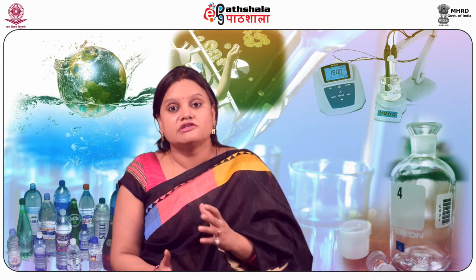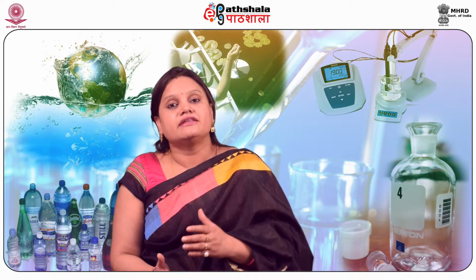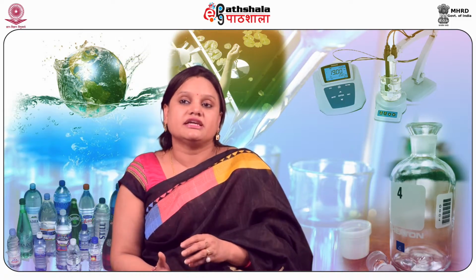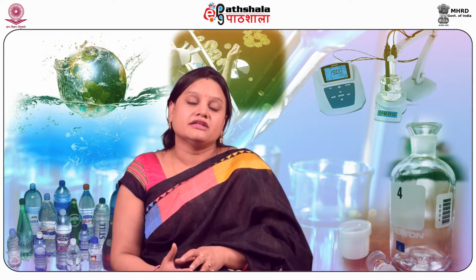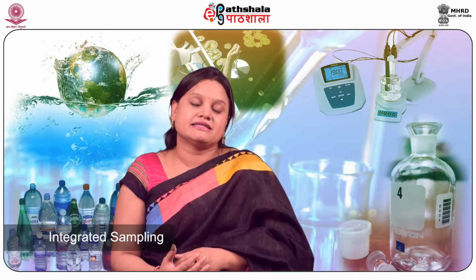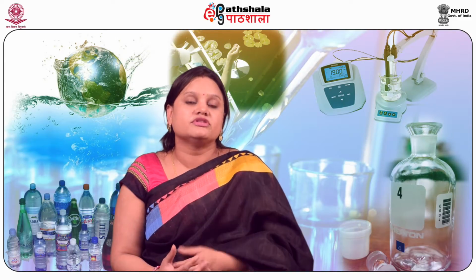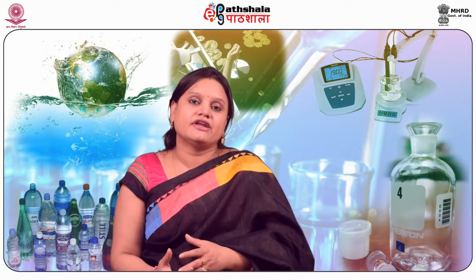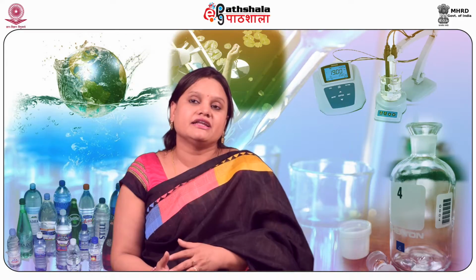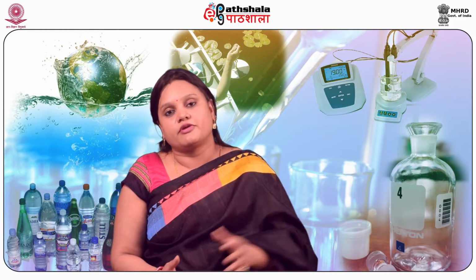Composite sampling is always done in big water streams and rivers, because it can be representative of the whole river body. And the third type is the integrated sampling. It is a mixture of composite and grab sampling, where we collect 4-5 grab samples simultaneously from different sites of the water body.